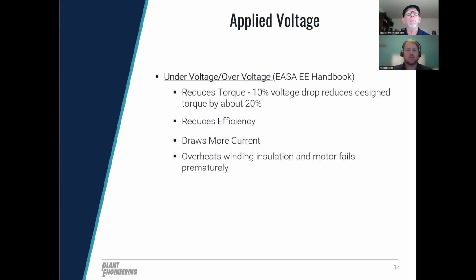But take into account that the grid voltage coming from your utility provider is going to be 480 volts, maybe even a little higher. So that 460 volt rating takes into account voltage drop in those distribution lines coming from the nearest substation or distribution transformer at your site.